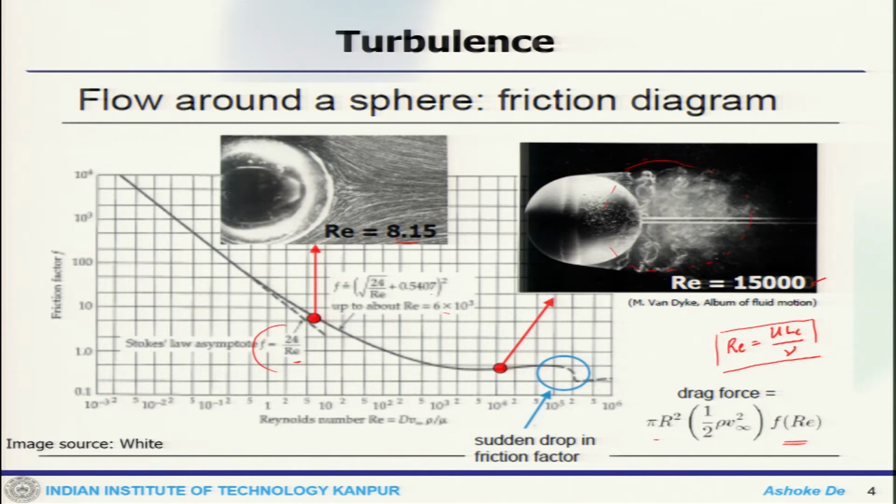That means they try to keep one side shiny and the other side rough. So, they maintain that roughness to make a difference in the fluid dynamics features. Here everything is turbulent. Now, if you make one side smooth and keep it shiny, the flow pattern will be different compared to the rough side.